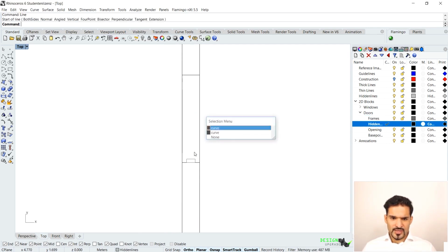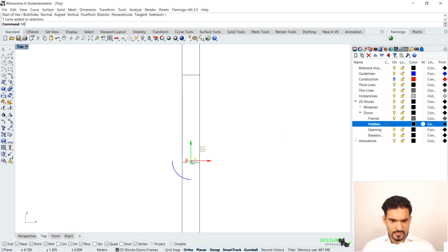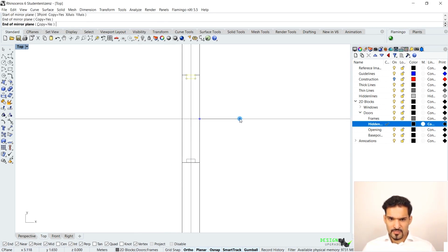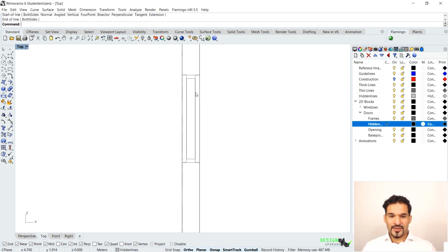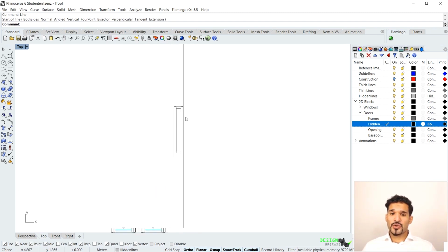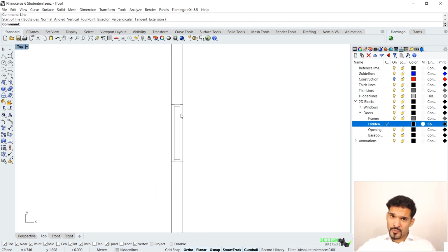What I'm going to do now is take this and mirror it using my symmetry line. And now I'm going to combine those two layers using my opening or my hidden line. So that's my hidden line. That is apparently wrong. Let's do it like that. So here I go, and then I want to make sure that I actually draw the opening of my door, right?